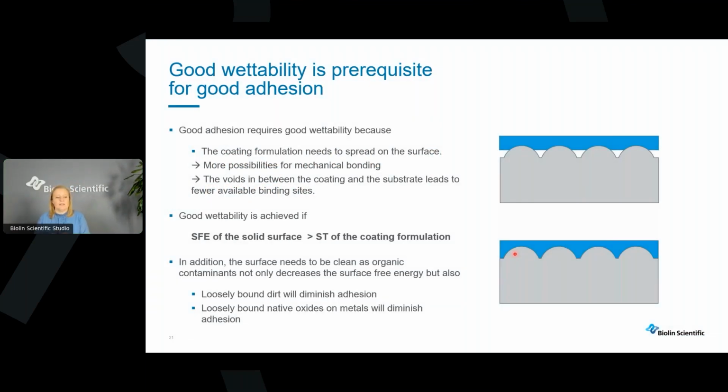The reason people would be interested in measuring surface free energies is to better understand wettability, and in that sense also adhesion of different coating formulations on your surface. If we want to achieve good adhesion between a solid and a liquid, then we need good wettability because the coating formulation needs to spread on the surface.